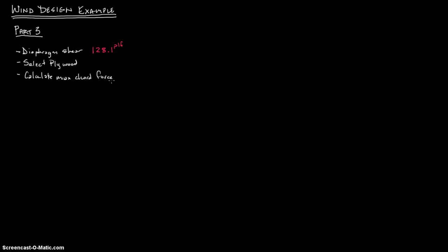This is on page 135 of the study guide. So we were going to the UBC table number 23-I-J-1, and that is reproduced on page 98, I believe. There's a lot of different things you could select. I'm just going to select what they did in the study guide. In their example, it says several diaphragms meet this requirement, and we select the following.